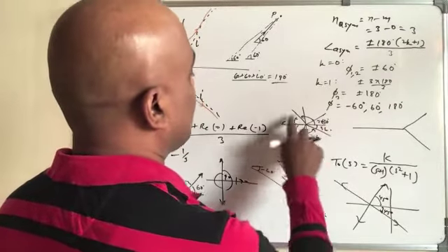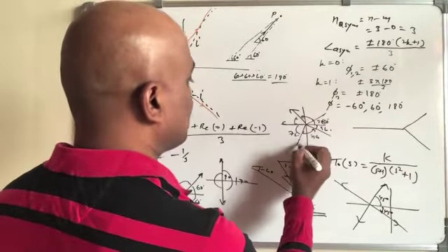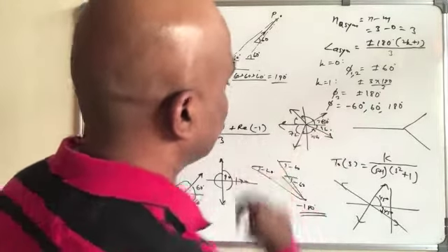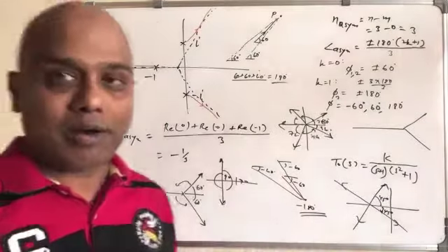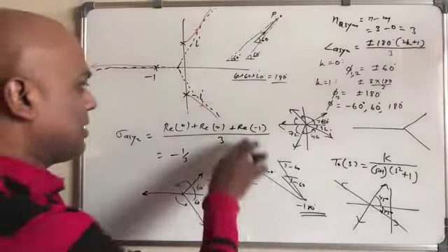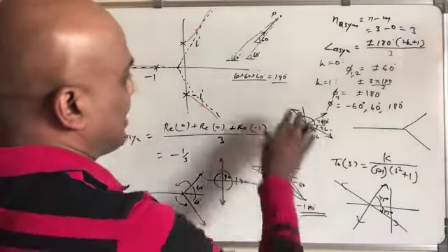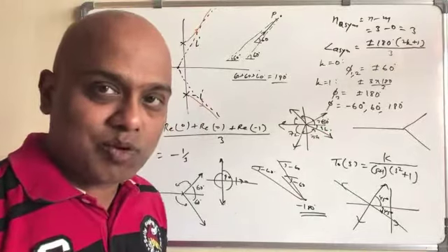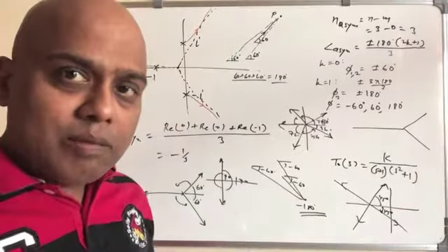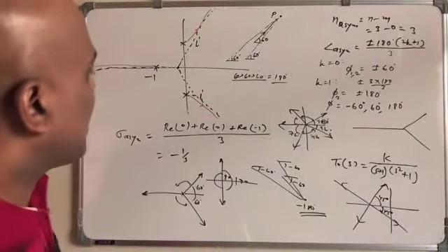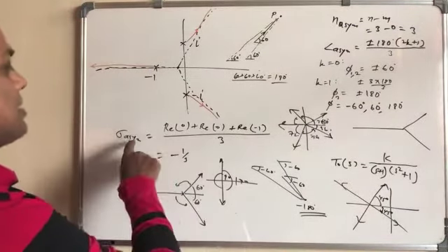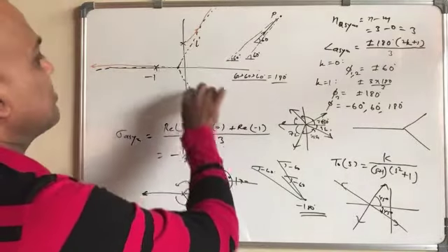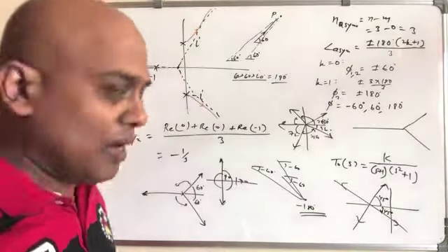So hence 5 of them. Yeah, so these go like this one, and this one, and this one. 5 of them, and so on. Yeah, so this is the origin. That's why at least you understood, and hence you can extend it to any number of poles and zeros. With this understanding, we can also derive the equation meaning at which point all the asymptotes are going to meet.